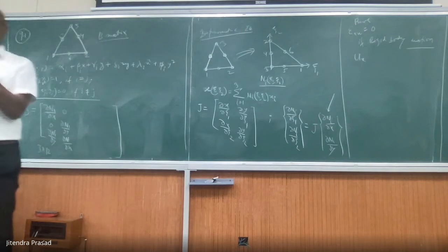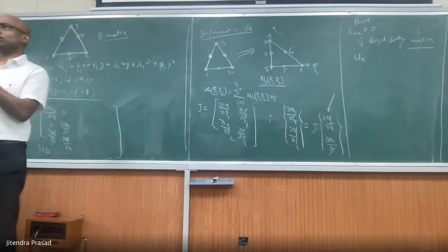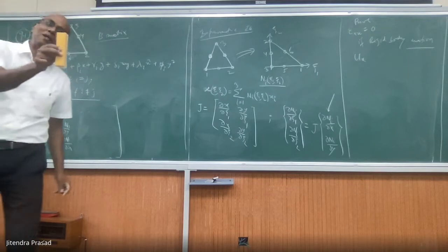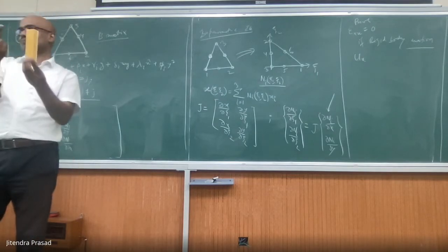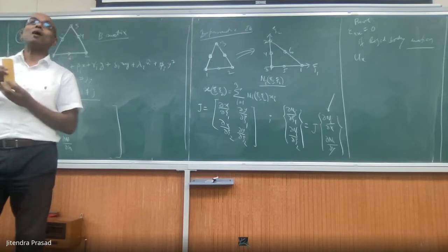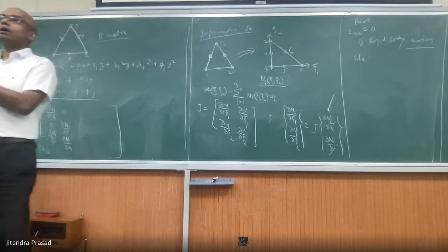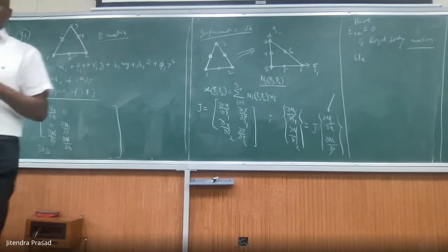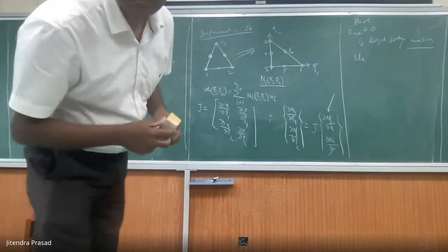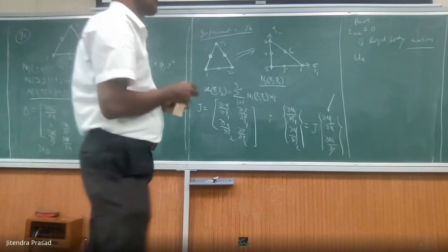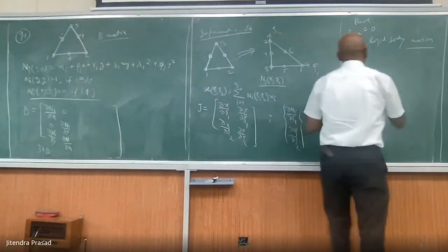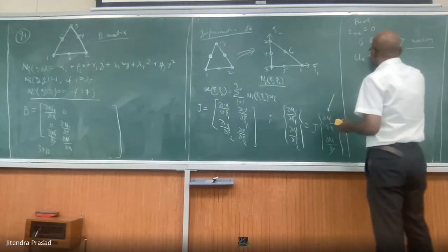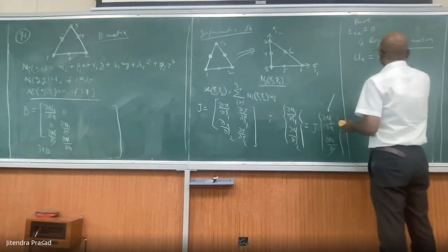If it has ux everywhere the same, right? Ux equal to 5. All points have the 5. It's possible, no? Displacement of all the points is equal to constant. This will be purely translation motion. Rotation will have, similarly, a relationship between them. So here it says rigid body translation. It's a translation. Rigid body translation really means ux equal to a constant.